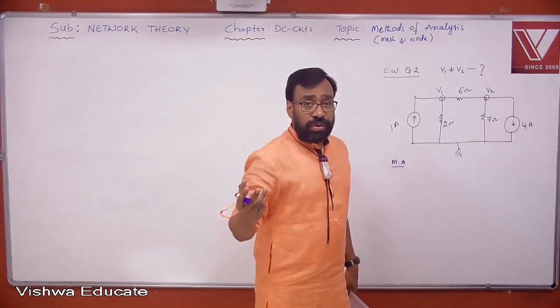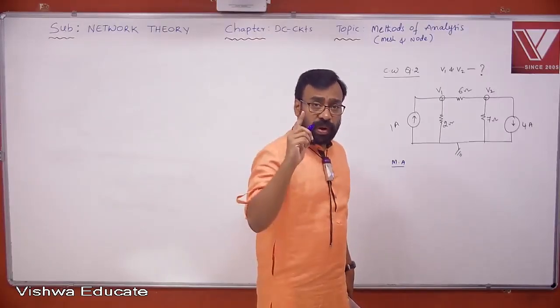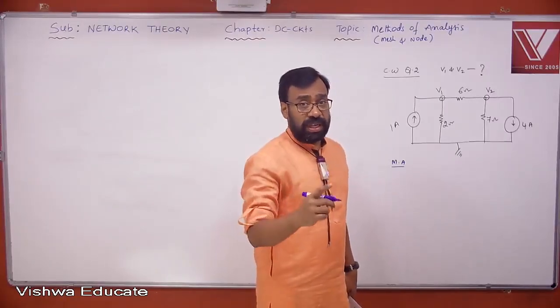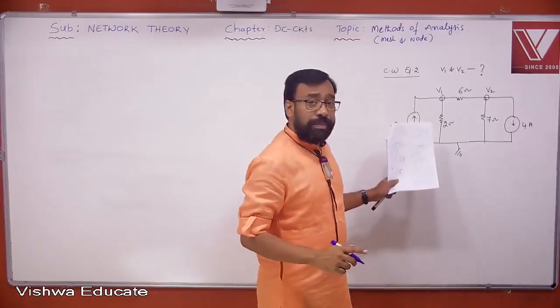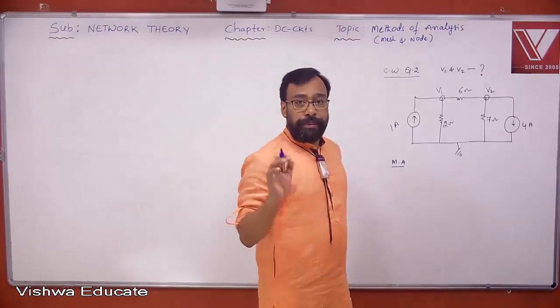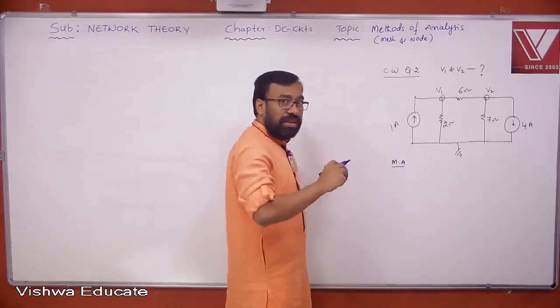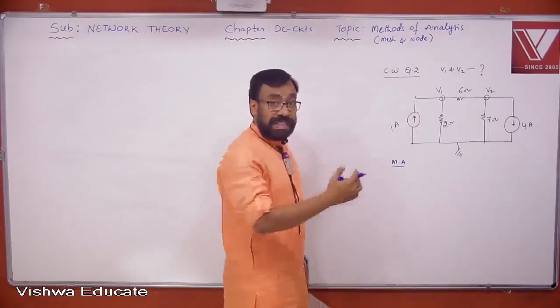So mesh analysis will give you one equation. Node analysis will give you 2 equations. The minimum number of equations required is 1, and that you can achieve through mesh analysis. Therefore, which is the best method for this particular problem? If I ask you the question, what is your answer? Mesh analysis is the best method. Yes or no? Obviously. But let us solve this problem using both the methods.